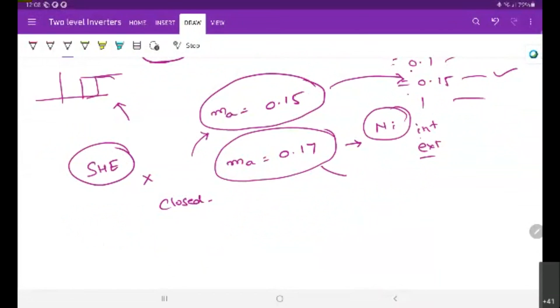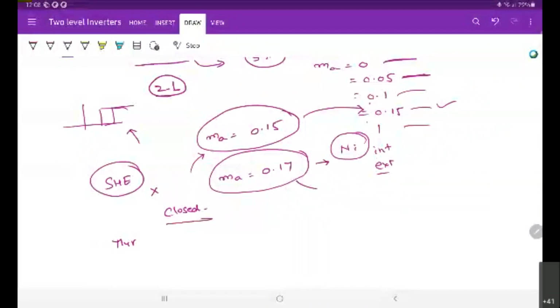This is the same for the thyristor also, right? For example, once the thyristor is turned on, we need to wait until the thyristor is extinguished. The same thing applies here also. So that means you cannot make modifications within a cycle. Whenever you make some modification, you need to wait for the next modulating cycle to apply the changes. So that's why it will affect the dynamic performance.